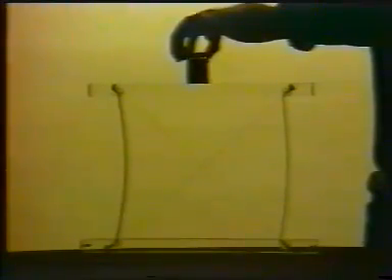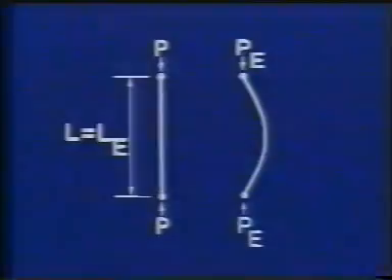The cross-bracing is provided to prevent translation of the column ends, a no-sway condition. The ends of the columns are effectively pinned by using V-shaped grooves in the supporting members. For this end condition, the buckling half wavelength is the same as the column length. The effective length is L.